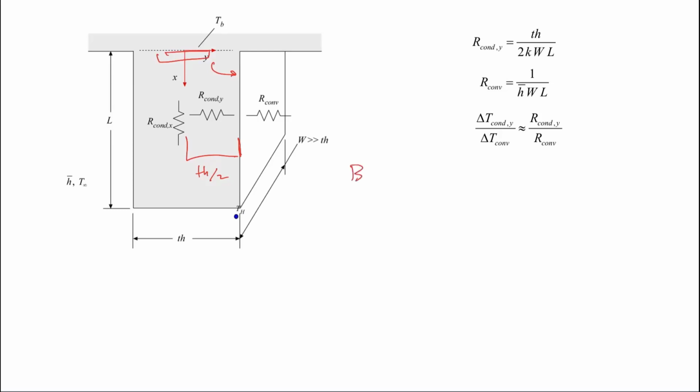Okay, so then you go through and maybe I first calculated the Biot number to be 0.01, and you come through and the Biot number is 0.02 or 0.005 or something like that. Is that important? We don't actually use this number anywhere in our solution. This is a method that we're going to use to justify an assumption we're going to make that allows us to get a solution. But you will never use the Biot number directly in any solution. So if we're arguing about 0.01 or 0.02 and which one it is, both of them are much less than 1. And that's the point, right? Yeah, question?